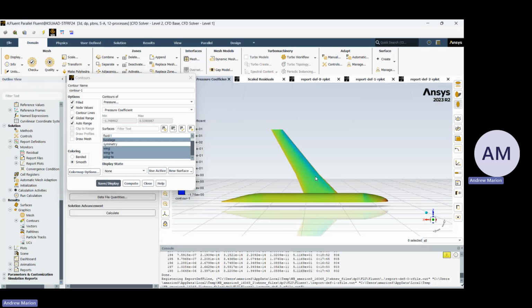One of them has to do with the wing twisting. It's because it also happens due to the way lift is produced in an elliptical fashion along the wing. So if you can make this ellipse end before the end of the wing, that will help because the vortex will form here, and then it will just get blocked by the wing. So that helps minimize it as well.